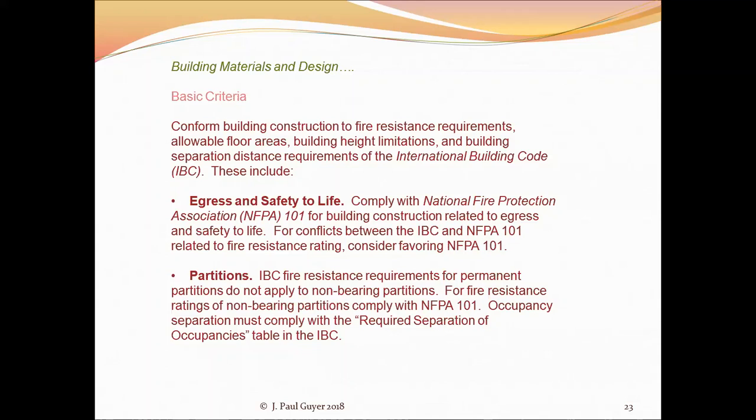So it uses an ASTM standard for testing the fire resistive characteristics of this particular wall construction. And using that ASTM methodology, it makes a determination of the appropriate fire resistive rating, 1 hour or 2 hours or whatever is appropriate. And so then the gypboard people just say in their catalog material, okay, if you construct your barrier, your walls this way, it will have a 1 hour fire resistive construction.